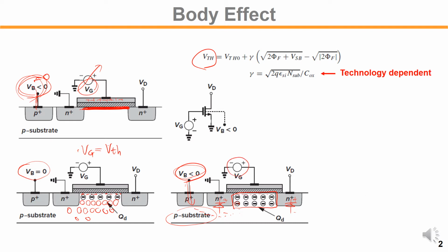So if you want to bring this surface voltage higher, we have to bring VG to an even higher voltage. Some additional delta voltage is required to make the channel inversion. Such a factor is shown here.